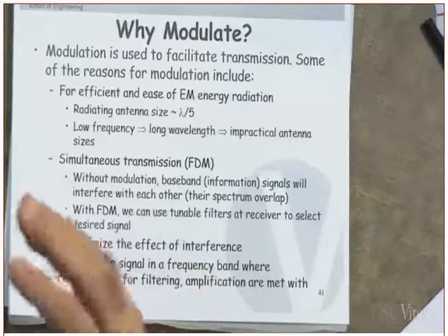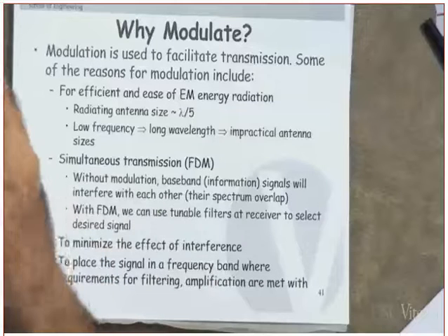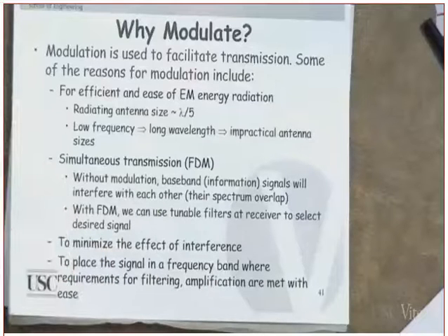Sometimes interferences are more concentrated in a certain band than others. Are you following me or not? If you look at the spectrum of coaxial cable, for example, you will see that it starts from roughly 5 megahertz. You might say, how come it does not start below that? Below that, there will be interferences from electrical or mechanical systems operating in the vicinity. Are you following that? Or some amateur radios, ham radios operating in the vicinity.